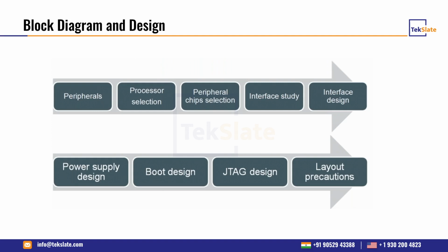It includes selecting the peripherals, basically identifying what peripherals the hardware needs. At the block diagram stage, you try to understand what peripherals it needs. Does my hardware need a USB interface? Does it need an Ethernet interface? Does it need any of the legacy RS-232 or 485? So one would identify the peripherals that are needed.